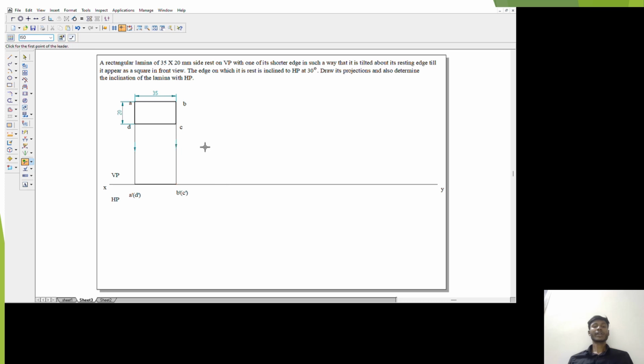Then draw a line towards up and mark its length up to 80 and the angle as 30 degrees, and then go to the square and copy the square and give a small dimension.